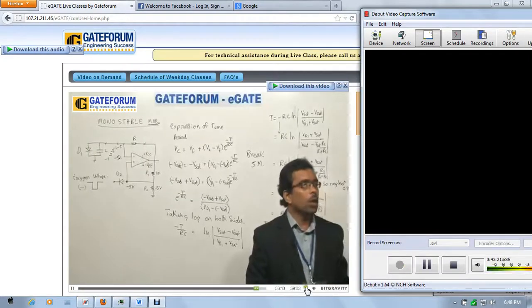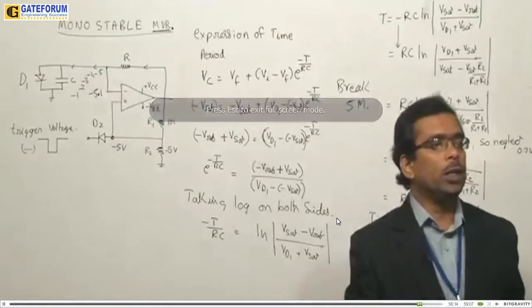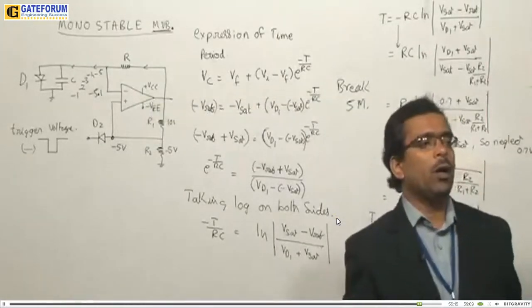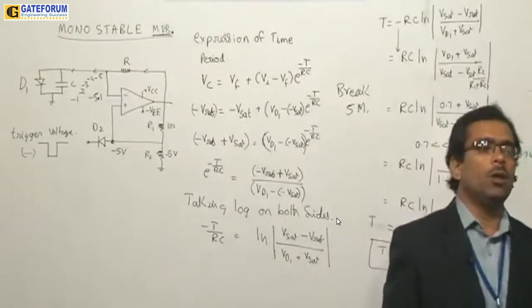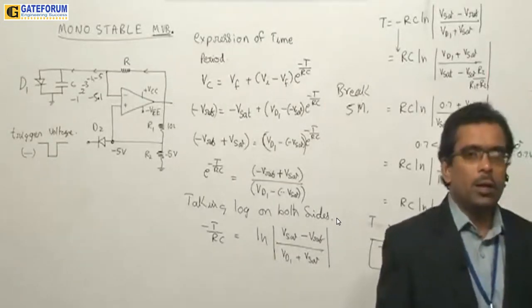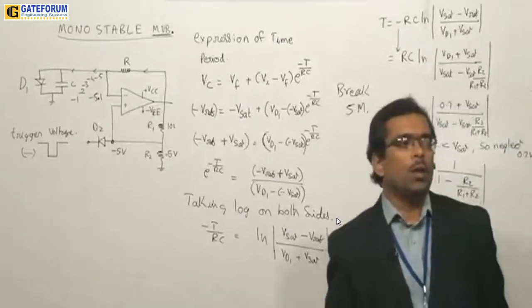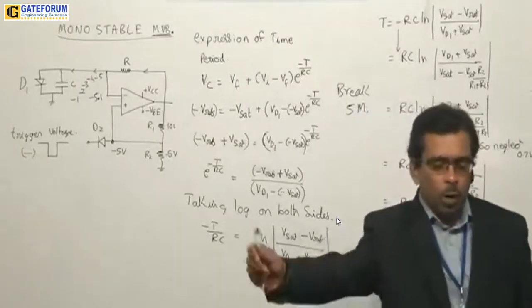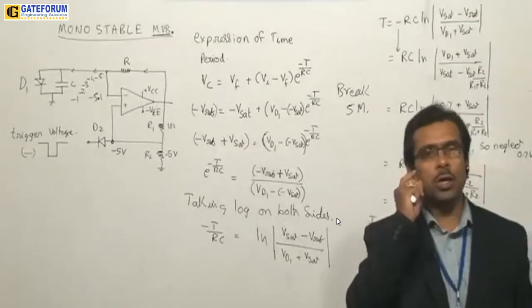Negative resistance oscillator. Suppose you take a UJT and connect one capacitor to the UJT, in shunt to its B1 terminal, then that circuit is going to work like a negative resistance oscillator. What do you mean by that? In a sense, when you increase voltage, current should increase.